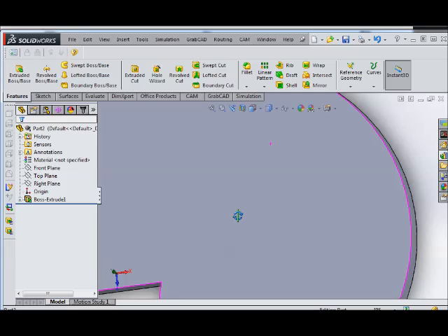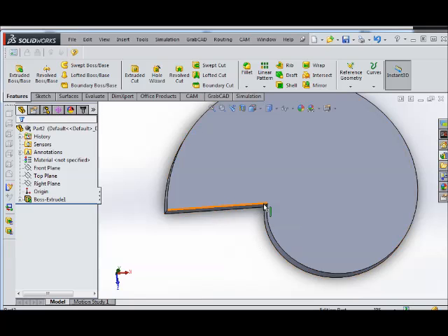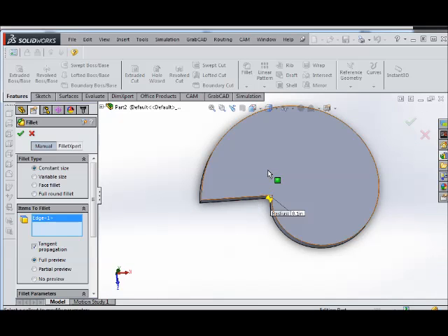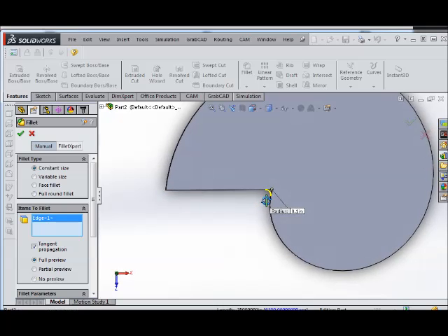And we can't mill a sharp corner like this, so we're going to want to put a bit of a radius here. You're going to want to make sure that your radius doesn't interfere with any sort of cam follower that you may be using.